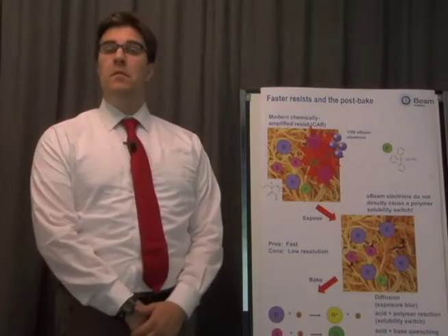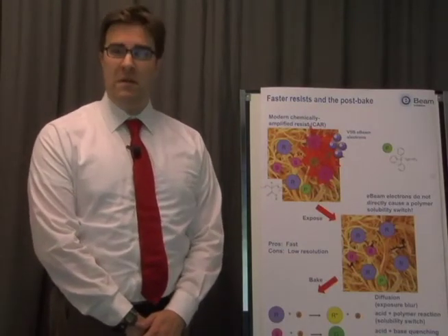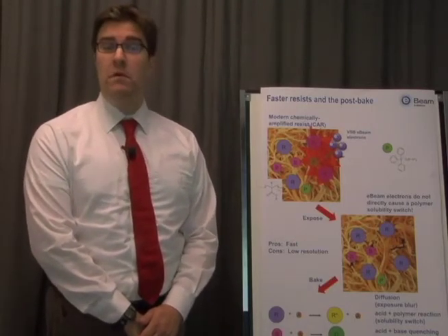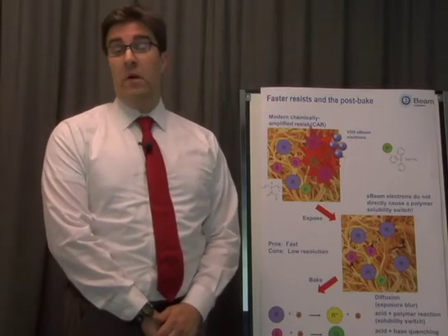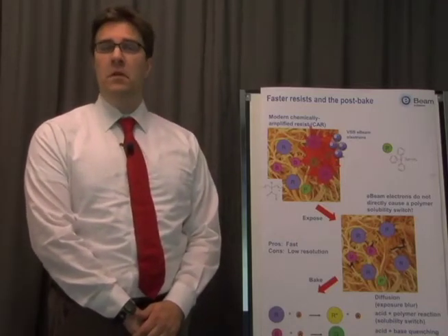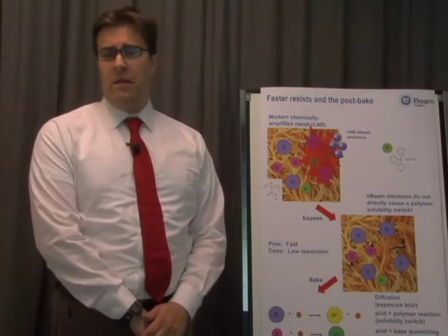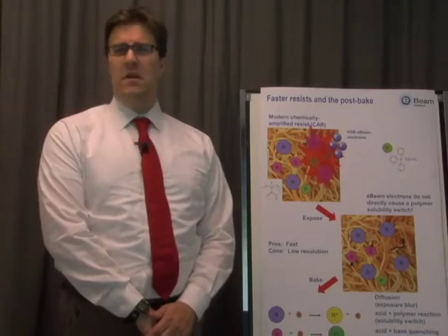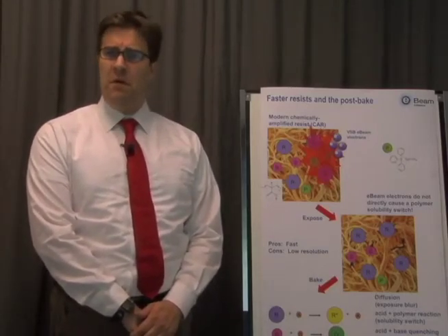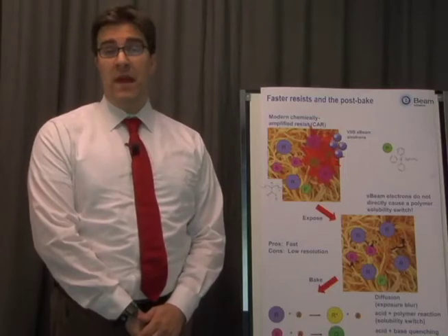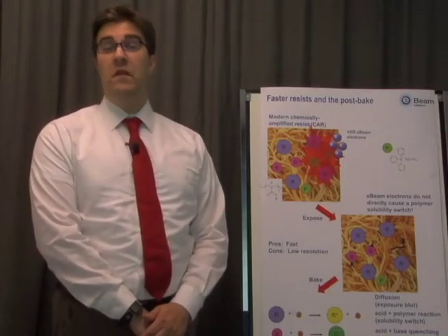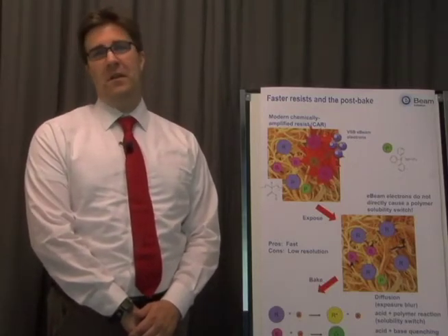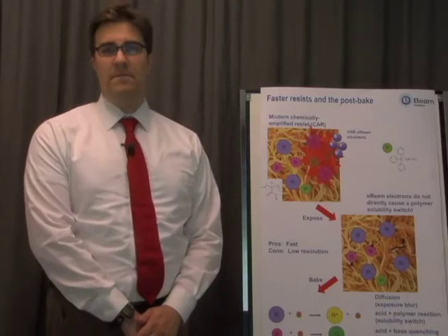So let's step forward in time where higher energies in the eBeam tools, as well as write time considerations for the entire mask process, become important. Now, one of the main reasons why a 50 keV eBeam tool was instituted was to reduce the forward scattering and therefore increase the ultimate resolution of the eBeam writing step. Now, unfortunately, conventional resists are relatively slow, and the high energy of the 50 keV eBeam made those resists even slower still, mainly because the secondary electron scattering cross-section goes down as the eBeam voltage goes up.